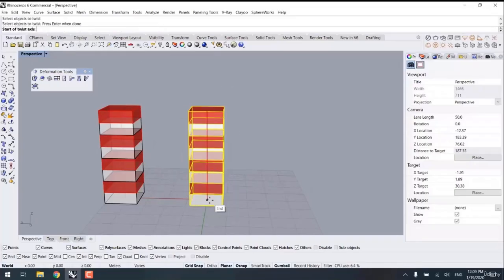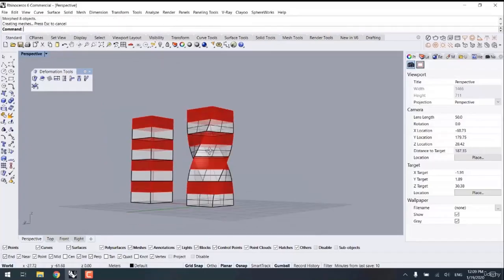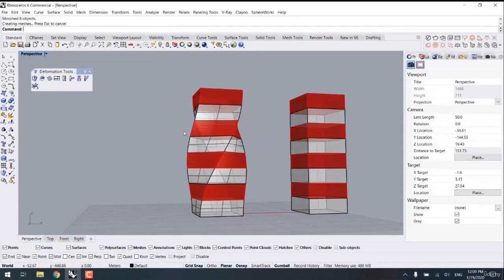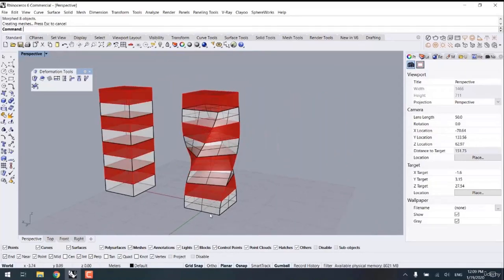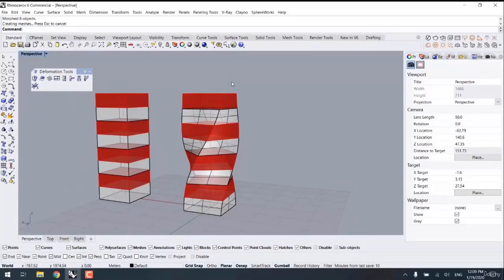Check it out. But let me set copy to no. Again, the axis, setting copy to no, 90 degrees. Check it out. As you can see, all of these objects are considered as a single object. I mean, even from the beginning to the end, they are considered as a unified object, and the rotation angle has been assigned to the entire objects.